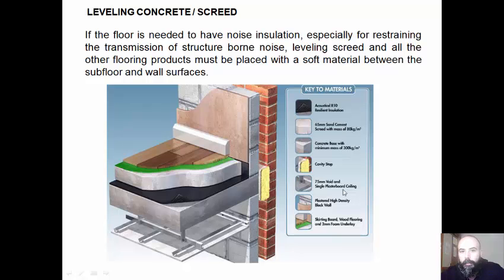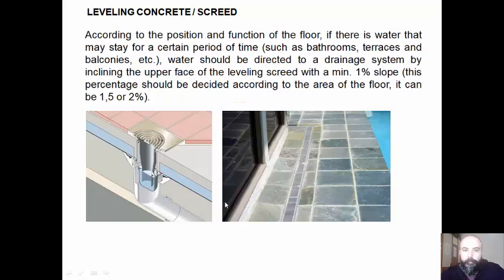If the floor is needed to have a noise insulation, especially for restraining the transmission of structure-borne noise, leveling screed and all the other flooring products must be placed with a soft material between the subfloor and wall surfaces.